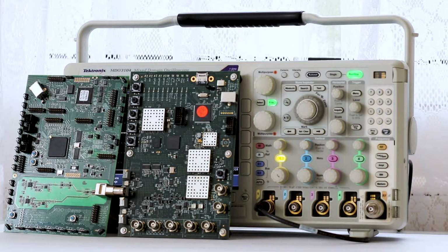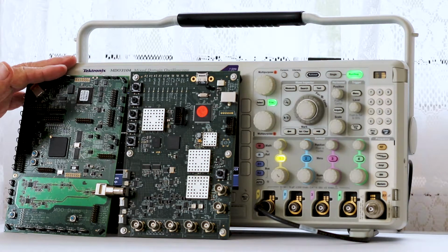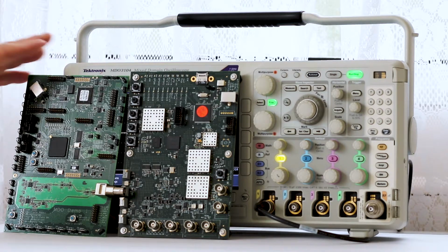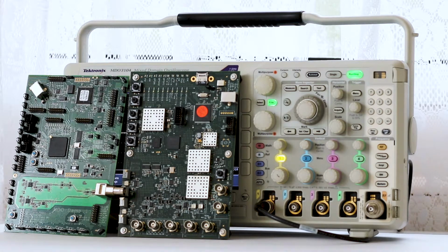Oscilloscope manufacturers offer demo boards that have a variety of signals. There is no reason why signals from competing vendors' boards cannot be displayed in your instrument as long as voltage limitations are observed. Utility voltage from a premises branch circuit is a possibility as long as hazardous voltage is not contacted and any voltage reference to but floating above ground potential is not applied to the probe's ground return lead.